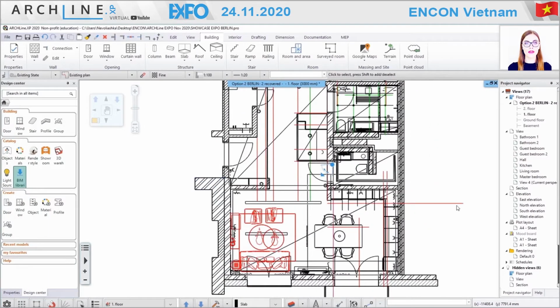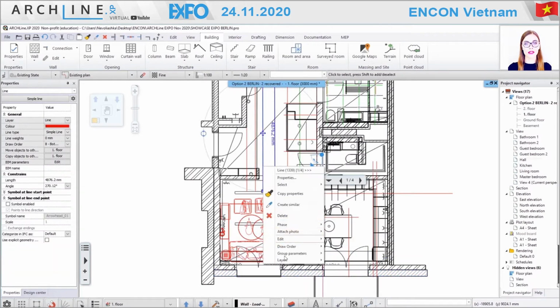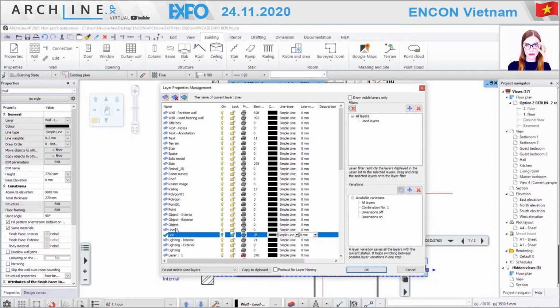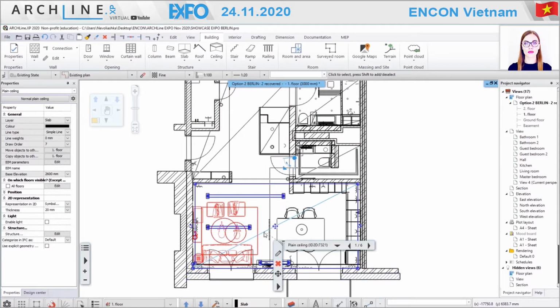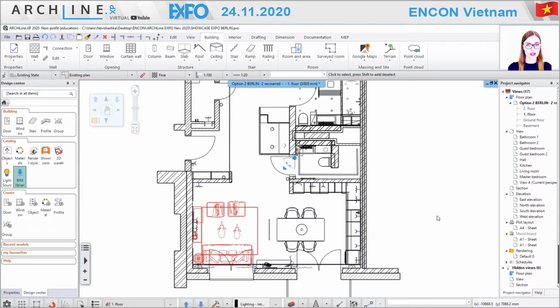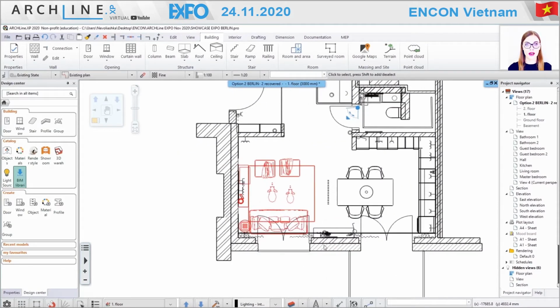That means we still have this working drafting process. We have all these lines that can be kept on purpose. And now we can see how I can switch them off when I'm using the line layer created by me. And for example, we also can switch right away from here the ceiling that disturbs our viewing. So that's it. Cleaner and maybe more understandable for the client, just in one click. And from here you can continue to work.